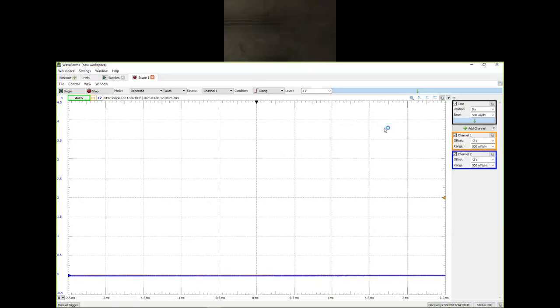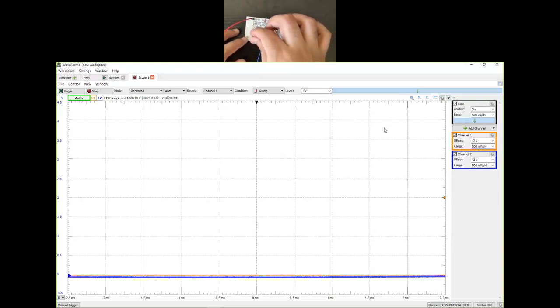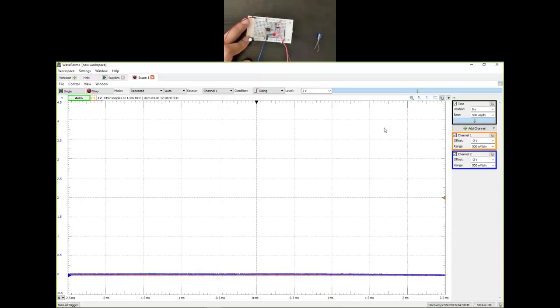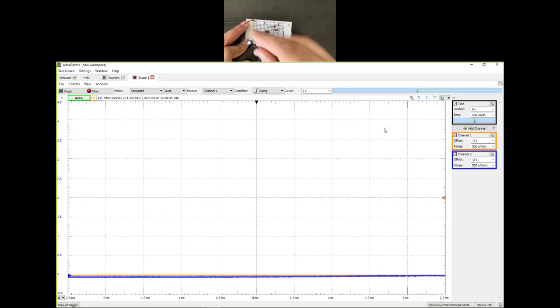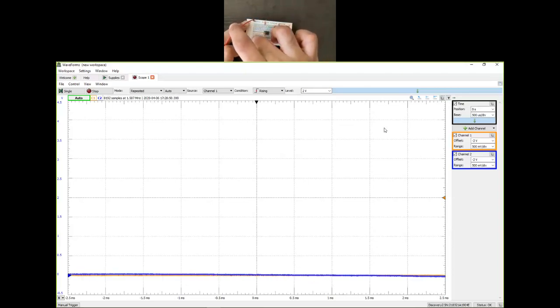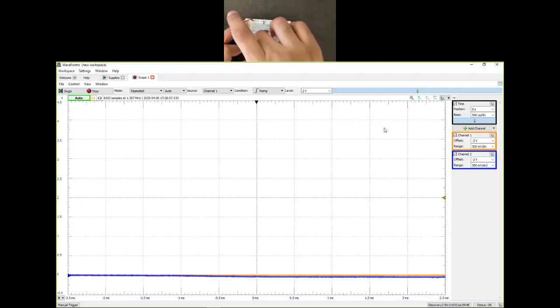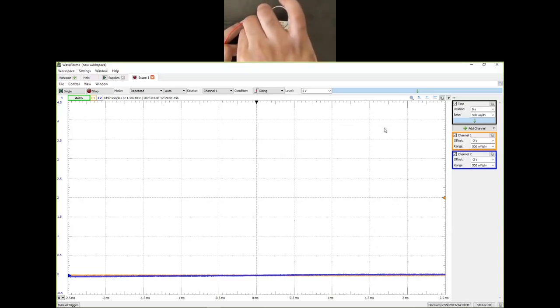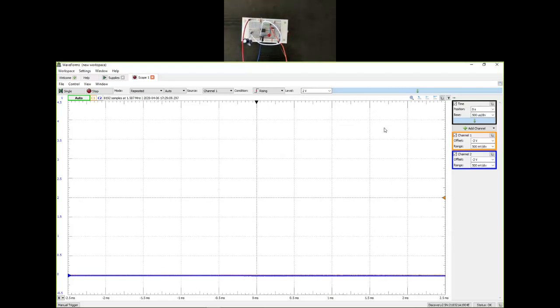Let me bring back my circuit. I've already removed my old capacitor, 0.1 microfarad. Now I'm going to place the bigger capacitor, 100 microfarad, between some point and ground, and I will also place my 47 microfarad capacitor from the same point to ground. So effectively they are now in parallel, and I will use a different wire, say a white wire, between pin number 2 and that same common point for the capacitors. So pin number 2 is now connected to two capacitors in parallel that both go to ground. Let me zoom in so that you can get a good view.